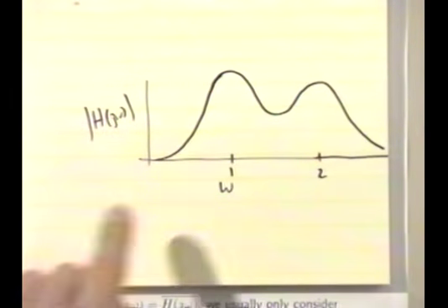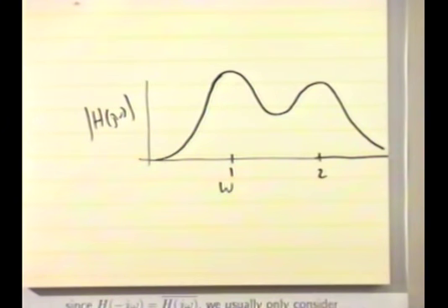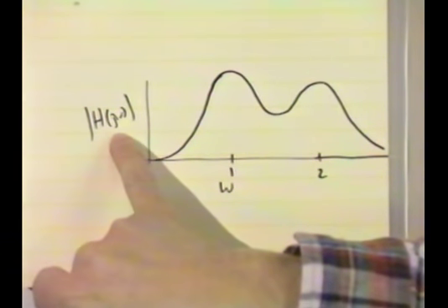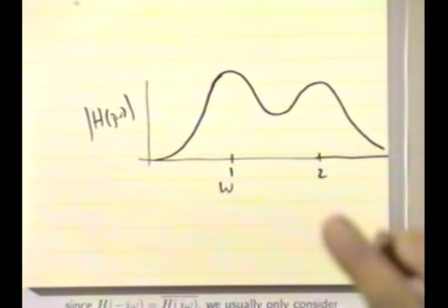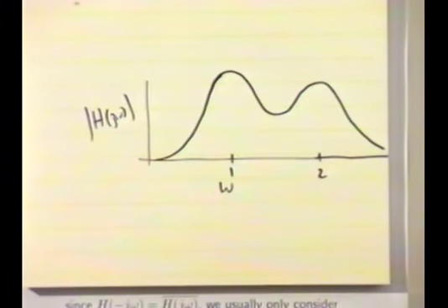The interpretation is this. If I put a low-frequency sinusoid into this box, what comes out asymptotically? What comes out? Well, if it's low, it's 0. The magnitude is here. The magnitude gives you directly the magnitude of the output sinusoid. And what is it here? 0. It's 0, right? So it says whatever this box is, when you put in a very slowly varying sinusoid, the output is basically 0. So in other words, whatever this box is, it doesn't react very much to slowly changing signals, right?